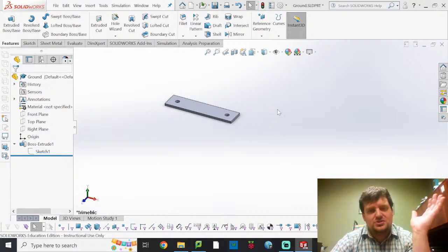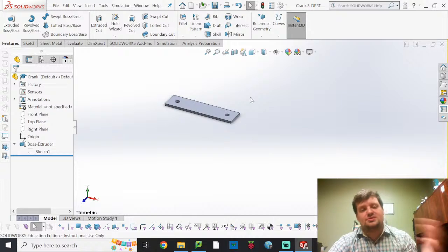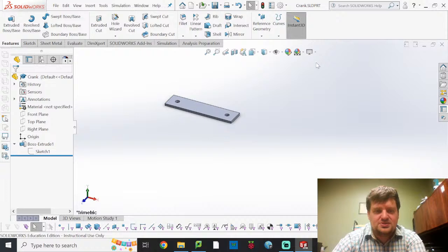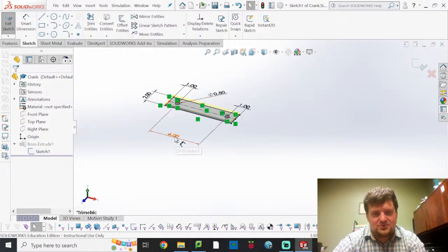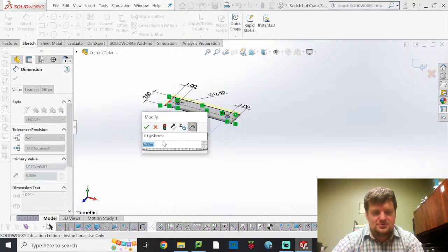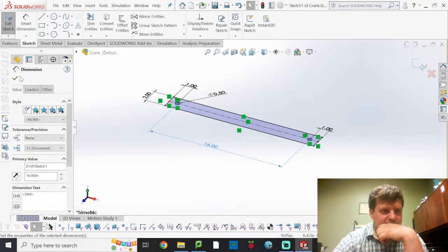Okay, now you will want to do some amount of work to make sure, according to I think Grubler's equation, whether or not this actually exists. No, it's the Grashof condition. You use the Grashof condition to determine whether or not it actually exists, because you kind of want it to exist before you do this. It's kind of important. But I know that this one will work, so I'm going to change this now to 16. Enter. This one will be my coupler.